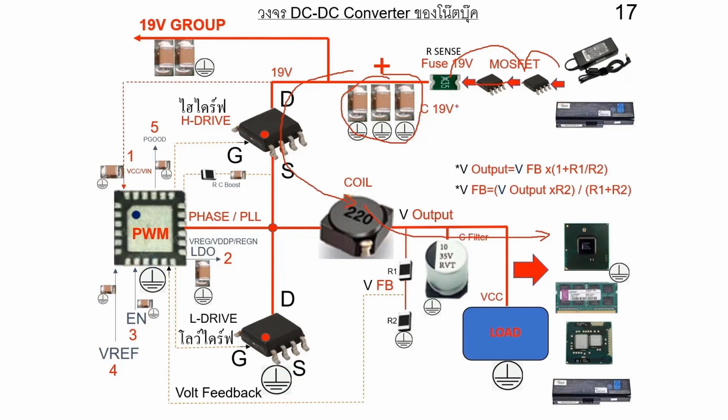When it shorts, nothing actually happens. The device still works. That's because it's a positive to positive short. If you think about it, this side is positive and so is this side. The power delivery circuit is just passing positive voltage. So a positive to positive short doesn't cause any issues. However, it won't charge the battery because the charging circuit controls this power delivery section, as I've explained before.